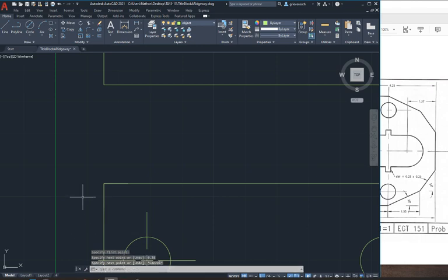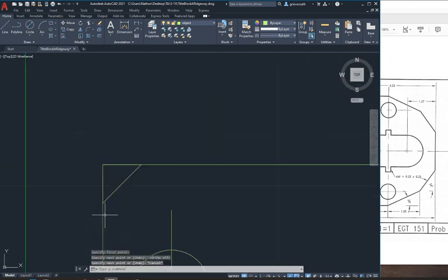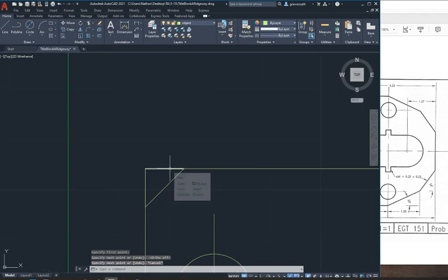Now you can't see these because I drew them all in the object layer. I could have made it more clear by putting them on a different layer, but if I mouse over, you can see how they turn white. Right? Now since those lines are on top, I should easily be able to snap and then turn ortho off and snap, escape, and there we go, that should be my cutout.